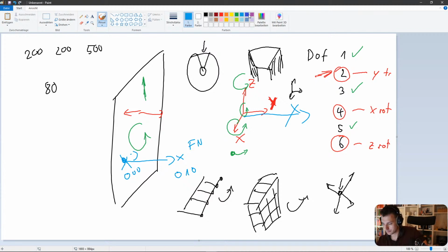They are oriented somewhat arbitrarily in space. So you have to constrain exactly in this direction only, and in order to do that, you have to do custom systems. Just imagine a custom system here where one of the directions correlates to the perpendicular direction to the surface, one here and one here. Then you can do that, and you have to associate the elements and the nodes to this new system. How this is done I may cover in a future video or episode, but it's pretty important.